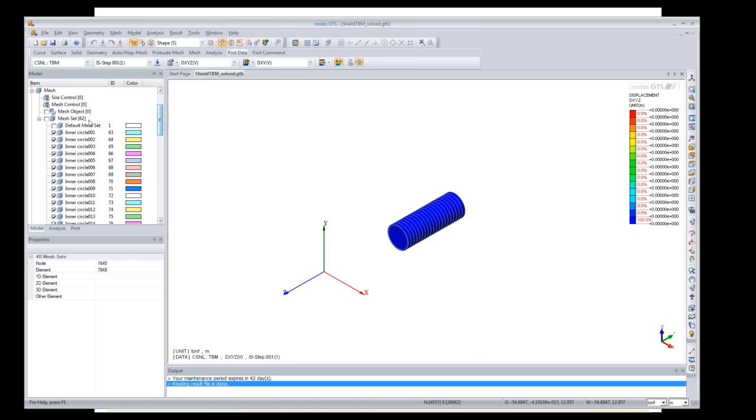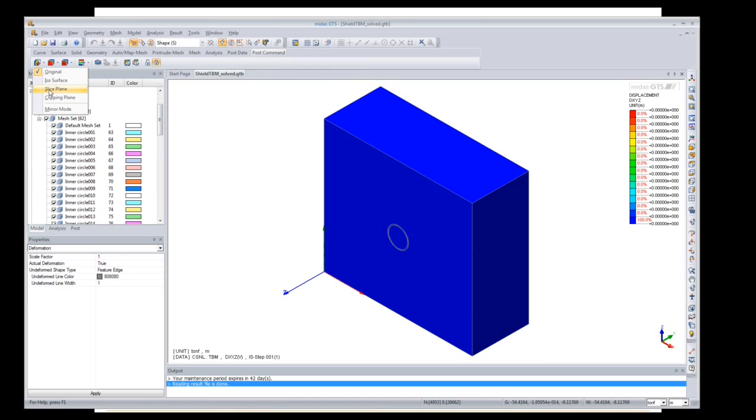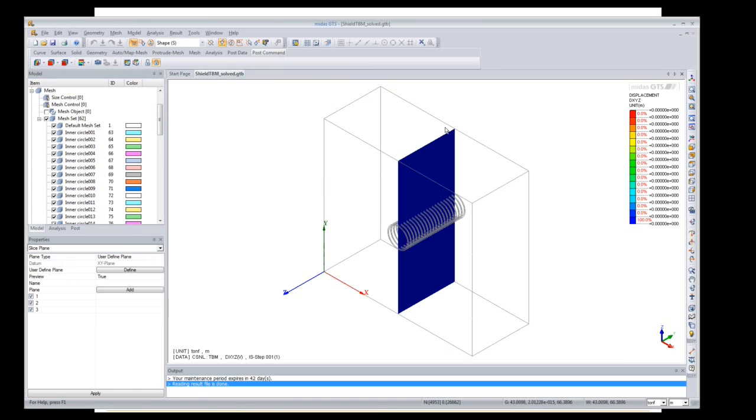And if you would like to get a complete picture, like a section cut, so what I'll do is activate everything. So this is a plot here, and I'll go to the post-processing command, and here I'll say I want to see slice cut. So in this way you can have results at any given section. So let me go to the post data, and let's say for this construction stage I want to see the force at a given place.